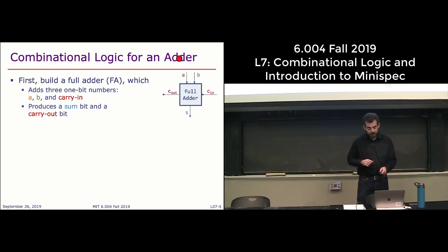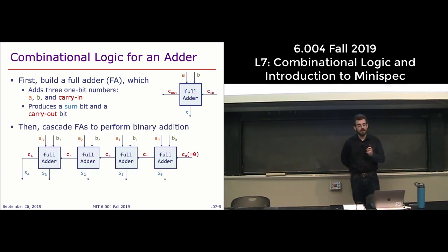So we get A and B inputs coming from the top, and then the carry in input coming in from the right, and then the output S comes out below, and C out comes out of this left side. And this is drawn like that and not input to output, because now that we have this circuit, which we'll derive in a second, we can compose multiple of these circuits to do multi-bit addition. Right? So remember, this circuit does a single step. Let's say that we wanted to do 4-bit addition.